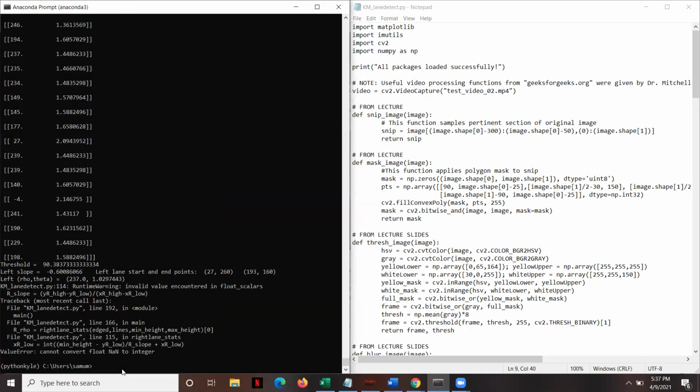All right. So as you can see, both videos feature some noise about the true lane lines, but the one in the brighter setting is much worse. This is due to the lack of contrast between the pavement and the white lines, which is a function of the pavement color and the glare from the sun. Also, another notable issue is that the code works noticeably better when tracking a solid line versus a dashed line. The negative space generated between dashes causes the line to jump in and out, while a continuous lane line is tracked more smoothly. So there's definitely some room for improvement from both a software and hardware standpoint.